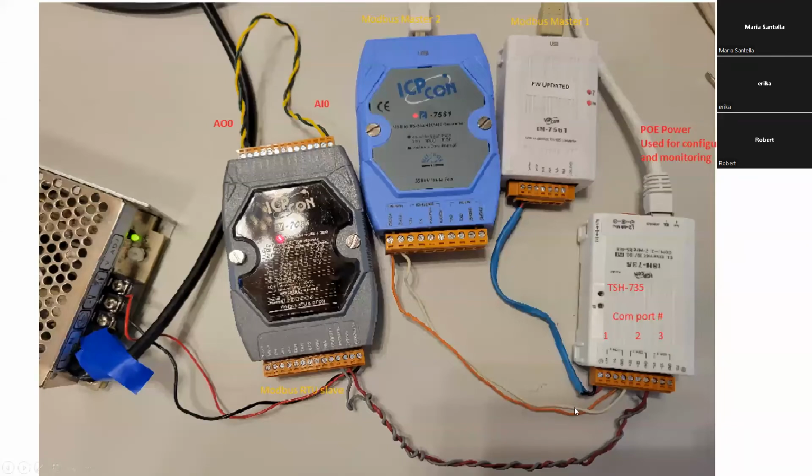So now for the live demo, this is my system. This is what I have set up. This is our M7026, which is a Modbus RTU slave device. I have analog input 0 and analog output 0 tied together so we can both see the live data happening and see data changing. This I-7561 is connected to COM port 2 of the module, but it's recognized as COM port 4 on my PC. And the TM7561 is connected to a second COM port on my PC through USB.